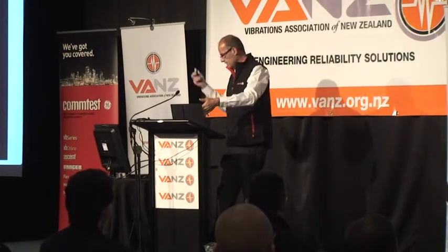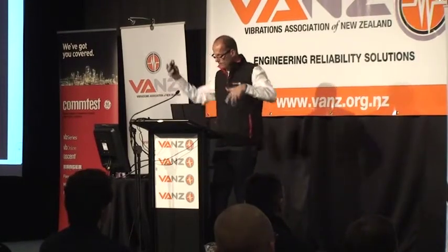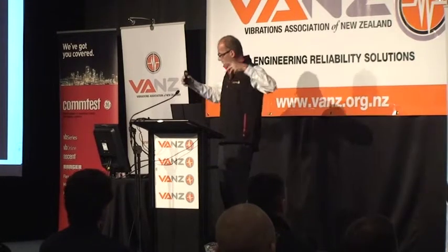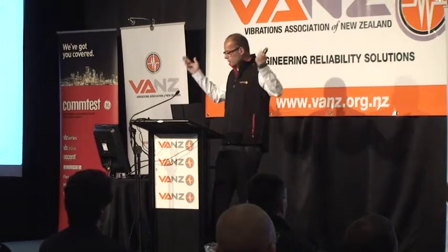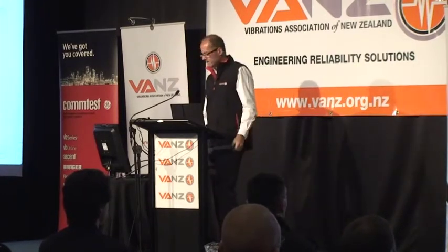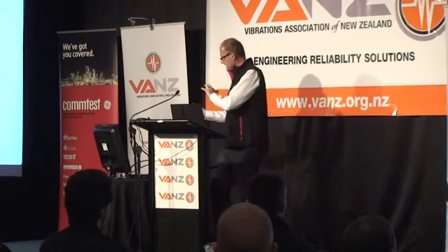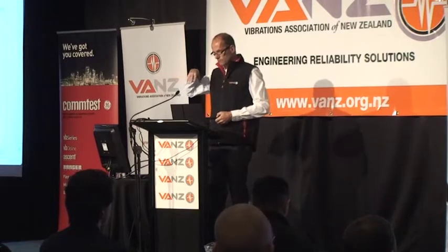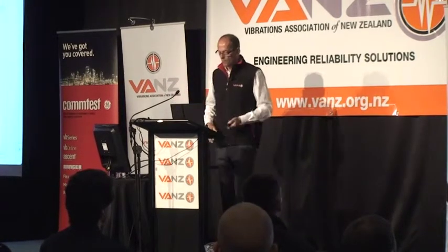We still see, in this case, with dynamic unbalance, we get a different phase relationship end to end. So I have to do a two-plane balance now, but I still get that 90-degree rule working. And so we can do all of our vibration analysis, we can look at charts, but if you understand the machine and understand how the spectrum is going to change, then when you see the spectrum, you'll know what's going on and whether you perhaps need to look at phase or time waveforms as well.